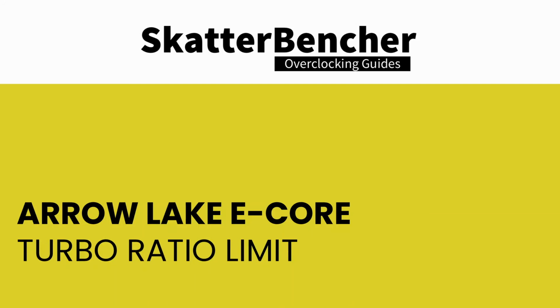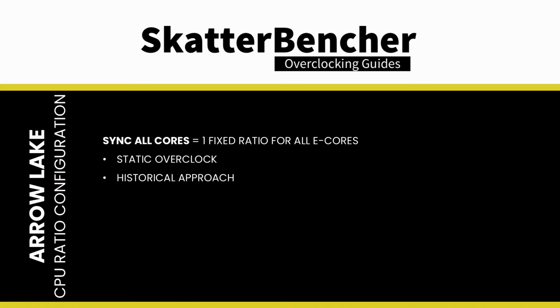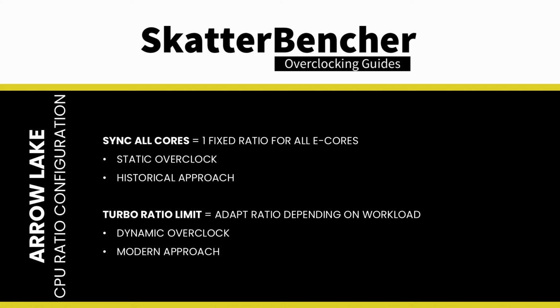Generally speaking, there are 2 ways to set the E-core cluster ratio: sync all cores or by using the turbo ratio limits. Sync all cores will set a single fixed ratio applied to all the cores. This is the historical method of getting a static overclock. Turbo ratio limit configuration allows us to modify the default Intel frequency specification and configure a dynamic overclock.